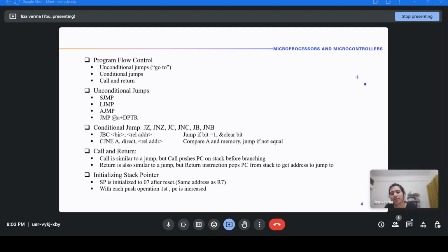From my understanding, in controller applications, the short jump is to save memory, and many times we may be jumping within minus 128 and plus 127. If it is a microprocessor-related application where we need to jump far, the 16-bit address may be useful. But in controller applications, obviously it is according to the application.